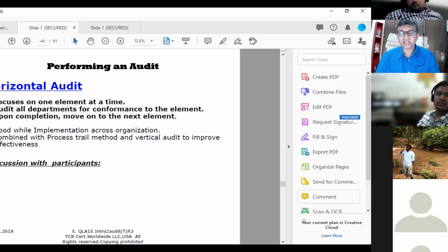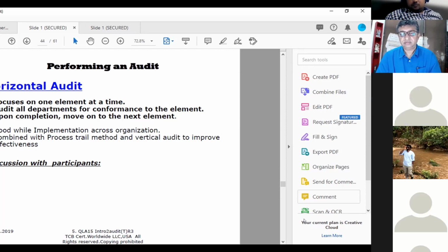If I say, okay, can you show me the chart recorder? A hydro test is normally done with a recorded chart. Not necessarily has to be with a recorded chart, but there'll be start time, end time, whoever has signed. I will check, okay, show me this person, and I will talk to him.